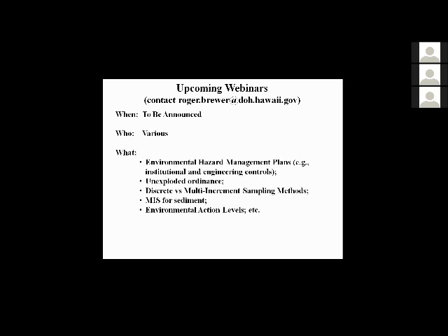We can. What you refer to is you have a decision unit in your building and you want to determine what the mean is for that. What we would do is we would have a sampler at each of the locations, and then when we get it back to the laboratory, we can set it up in our system to desorb each one of those traps onto a focusing trap and then analyze that focusing trap to give you the measurement from all locations with one analysis.